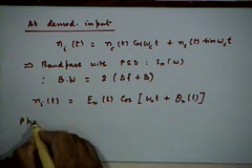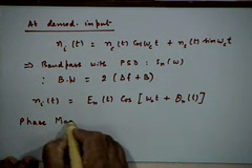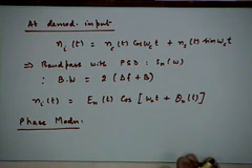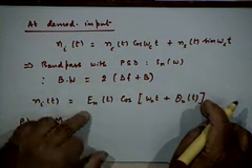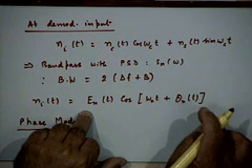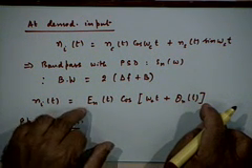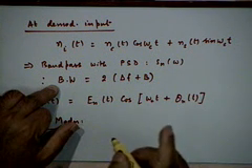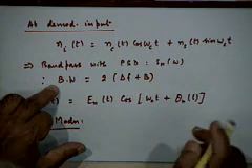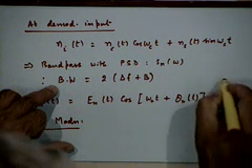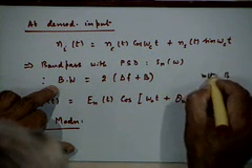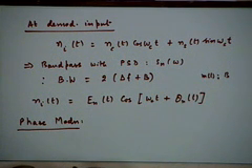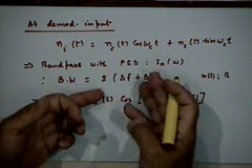Let us first consider phase modulation. And before we proceed, one point I would like you to understand is the implication of the fact that your noise has this bandwidth, whereas your signal, by signal I should say message actually, has a bandwidth of B. So m(t) has a bandwidth of B, but the noise that you are considering at the demodulator input has a much larger bandwidth.